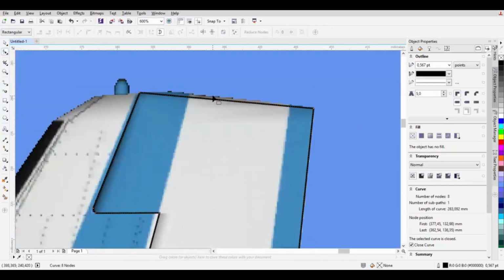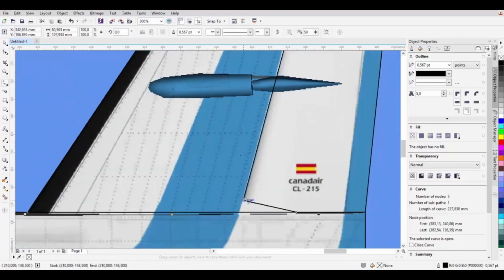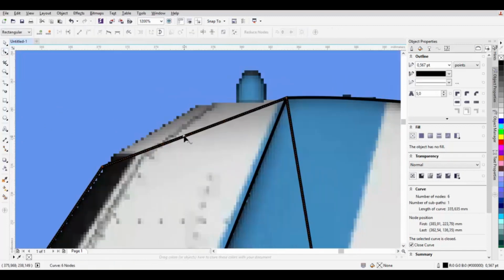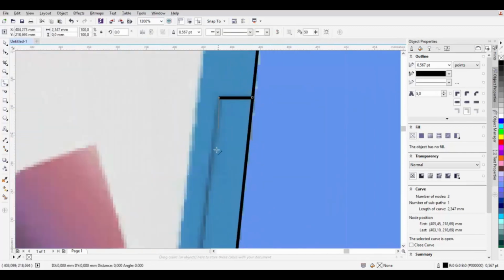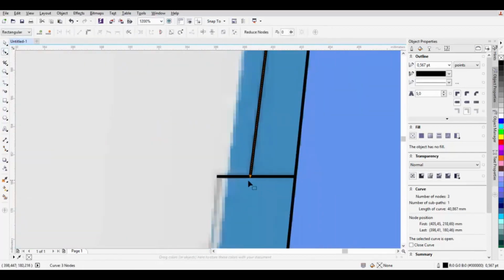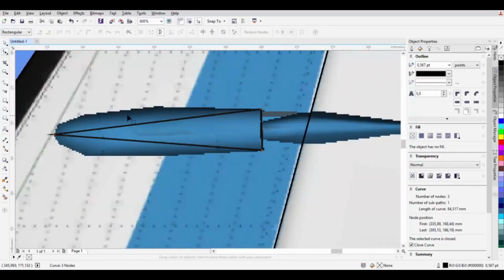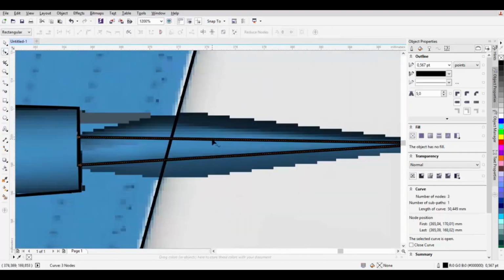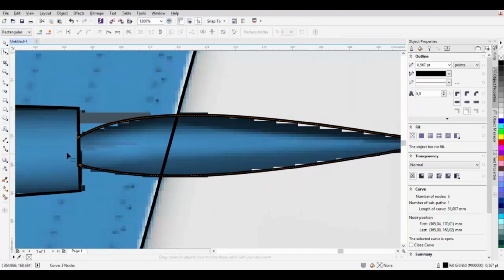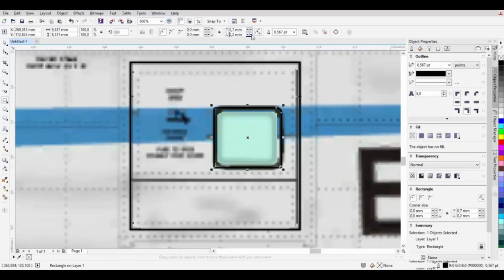Letters are also used, and becoming more prevalent, with the most common letters being A through E. The letter A is 8.5 by 11, B is 11 inches by 17 inches, C is 17 inches by 22 inches, D is 22 inches by 34 inches and E is 34 inches by 44 inches. There are additional letters, such as D1 at 24 inches by 36 inches, E1 at 30 inches by 42 inches and additional sizes unique to even larger formats but generally reserved for intercompany operations. The remaining digits identify the drawing. Many firms have modified this basic system to conform to their needs. The letter or number depicting the standard drawing size may be prefixed to the number, separated from it by a dash.